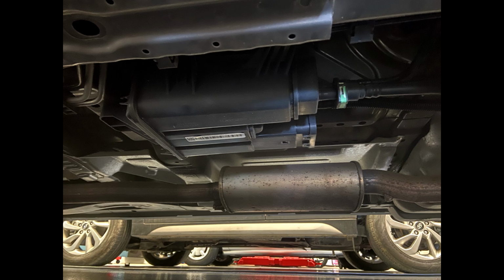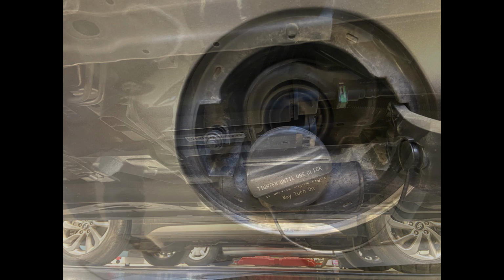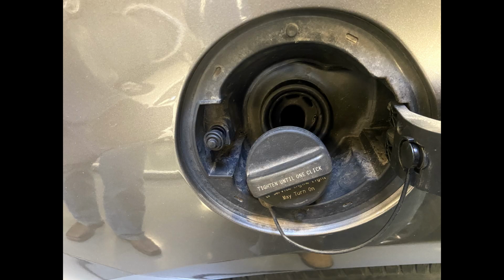And another test would be the small leak test. This would be a 0.02 of an inch leak. This is done by monitoring the natural vacuum of the system as the fuel cools after running. The system can run up to 40 minutes after key off. This is done by closing and sealing the system and watching as natural vacuum builds.